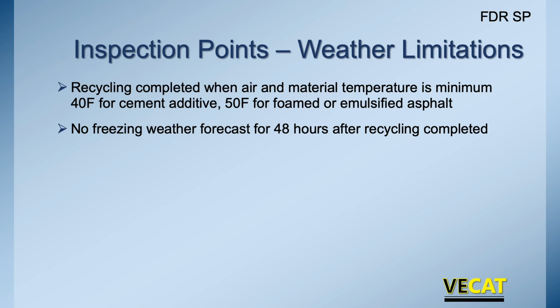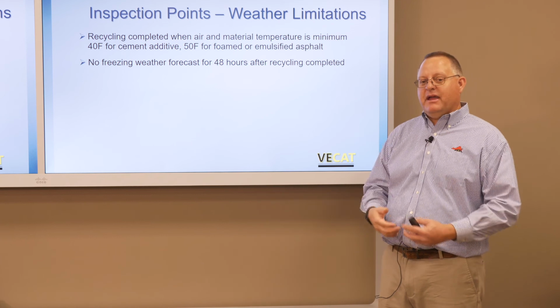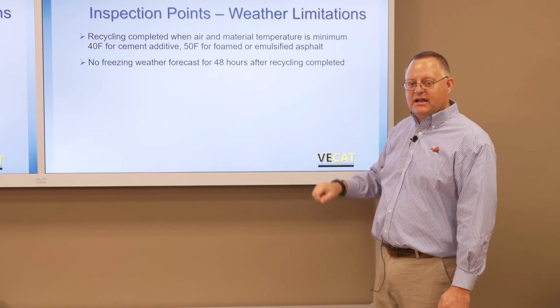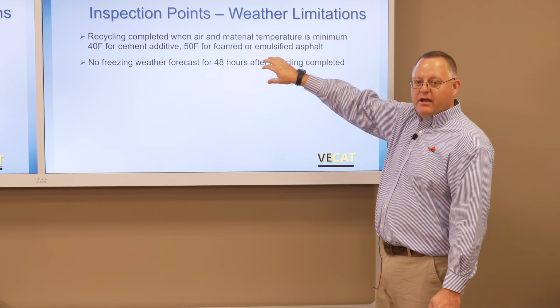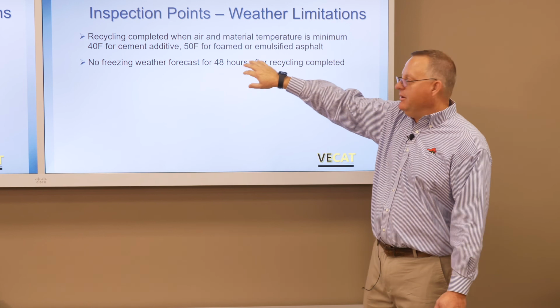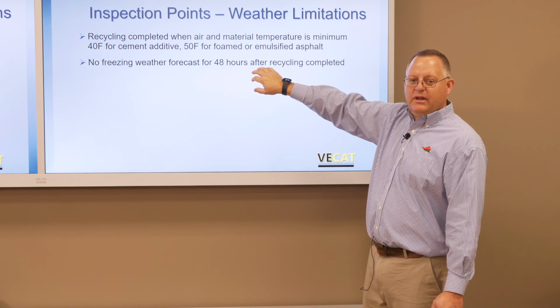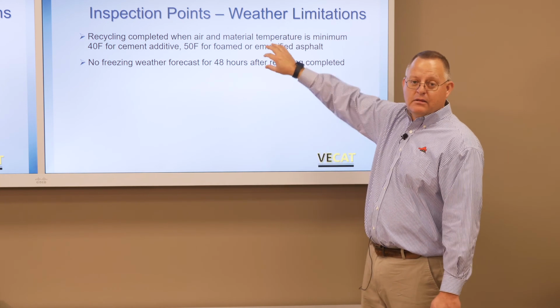Why? Remember, we're adding some water to this. If there's still water trapped in that pavement, or in that material, that hasn't been released, hasn't evaporated, and it freezes, water, when it freezes, expands. The expansion can break the bonds. It's in that stabilized layer, and it's detrimental. So when you're looking to do this process, and you're in the 40, 50 degree range, you need to be really looking at the next 2 days. Are we expected to see any freezing temps? And if so, we're not doing FDR.